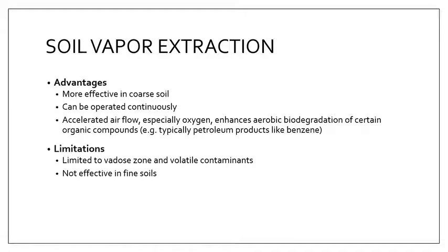The limitation of this method is that it's only limited to your vadose zone and to your volatile contaminants. So you're just dealing here with your vapors. And it's not effective in fine soils, because fine soils have small air permeability. Oh, sorry, water also has low permeability in fine soils.